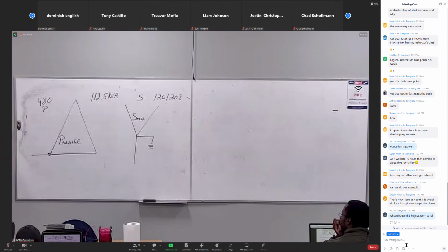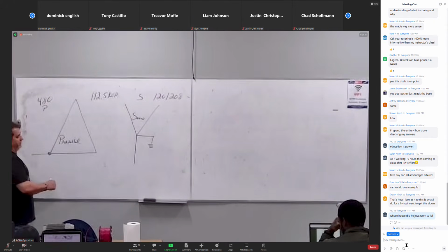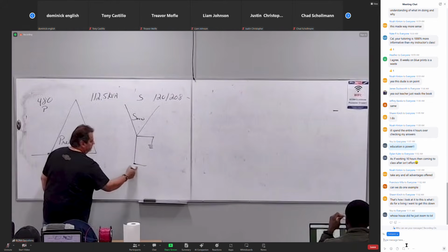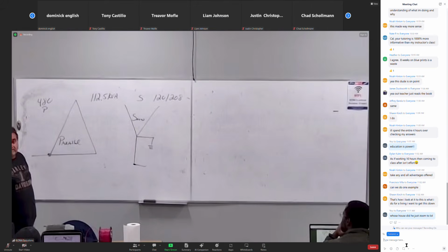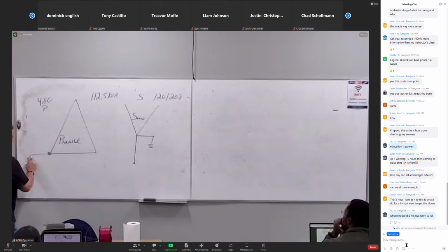Which way can that voltage travel? Everybody looks at the circuit itself and not at input and output. Even if this was an output to a secondary, how many coils contribute to that phase? 2, that makes it parallel. Go over there, input or output, right? This one right here, how many coils contribute to that? Or how many do I put into there? It has one path to go. That makes it a what? A series circuit. It's how you perceive it, right? How you look at it.